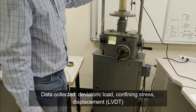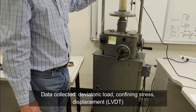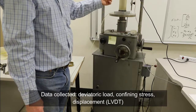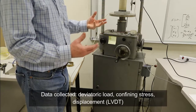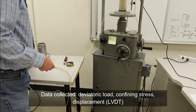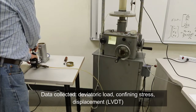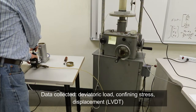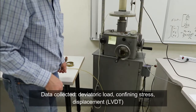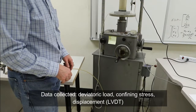The data we're going to take includes the load, which again is the deviator load. The isotropic confining stress in all directions, again, is supplied by the vacuum. So we want to set that vacuum regulator to the value that we want. And for these tests, typically that's going to be around 1/2 an atmosphere. They'll vary a little bit from test to test, so we'll need to make sure you have the right value for your test.